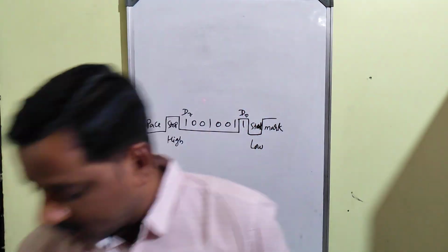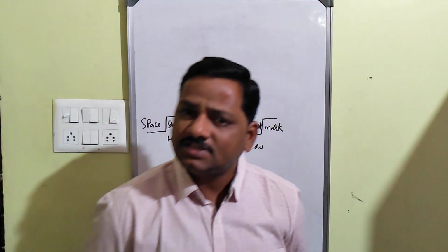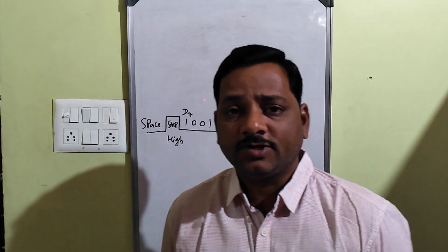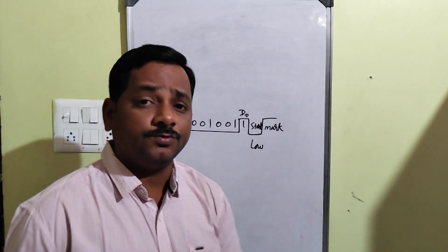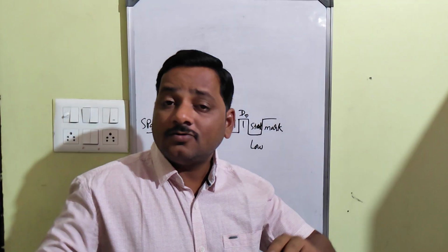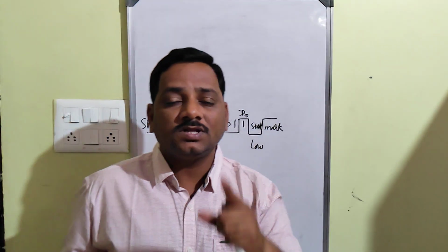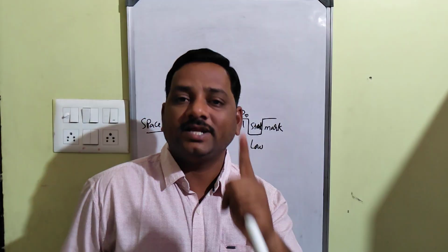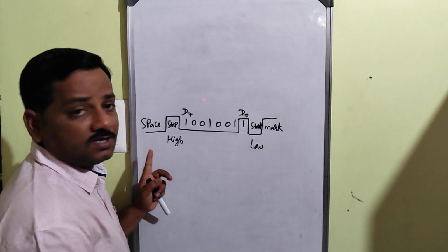If this is clear, now let us move on to the next concept, that is just one simple important thing I want to tell you about the serial communication which we use in a microcontroller, that is baud rate. Okay, so after transferring this package, I think now it is clear for you how we transfer. We are not going to transfer only the 8 bits, we are transferring with a start and stop bit. So totally if you want to transfer one character or one 8-bit data, we need to have 10 bits over there. One for start, one for stop.